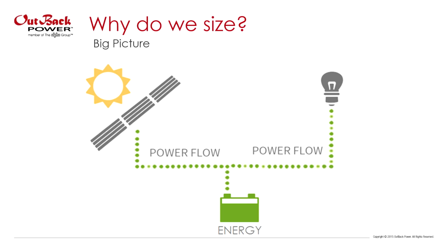So here are some things that are important that can make or break your system. And that is the accuracy of the solar data that you have in your area. Like I said, if you don't have a lot of sun in your area, for example super north, you're going to need more modules. And the second thing is the accuracy of the loads. And we'll emphasize this later, that having that information accurate is going to be really important when you're sizing these systems.